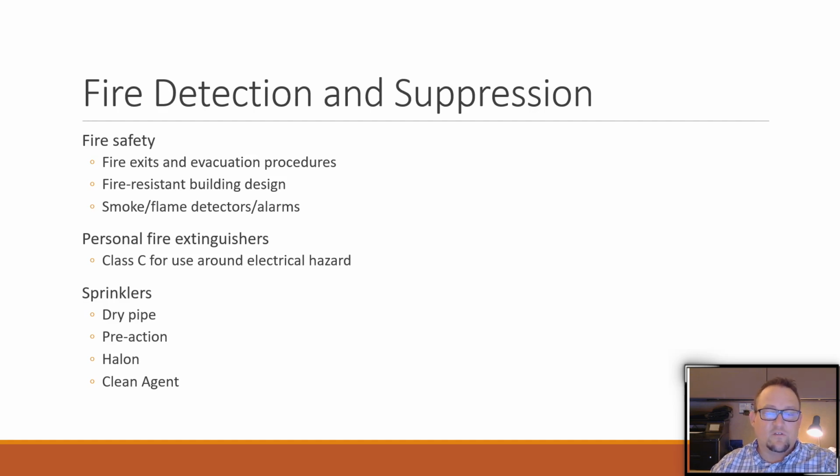These are very dangerous for people because if I push this button, you better get out of the data center because it's going to take all the oxygen out of the air to kill the fire. But what happens with that? Well, I need oxygen to breathe. Okay, I don't know about you, but I need oxygen to breathe. So that's what a halon is. And then you've got the clean agent, which is a powdery substance which sucks to clean up after it's all said and done. And I don't like that one, but it is an option. At least you can breathe through that one, right?